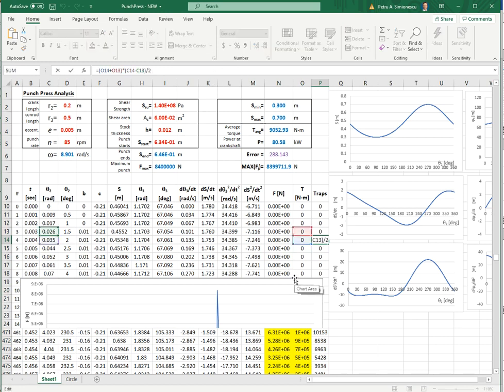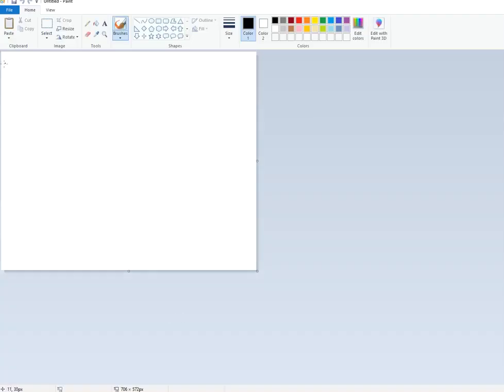So I take the torque at k value plus the torque at k plus 1 value, and then times the change in theta divided by 2. You may want to refresh your memory on how to calculate a trapezoid. This is actually going to be a particular case of a trapezoid where I have it like so.